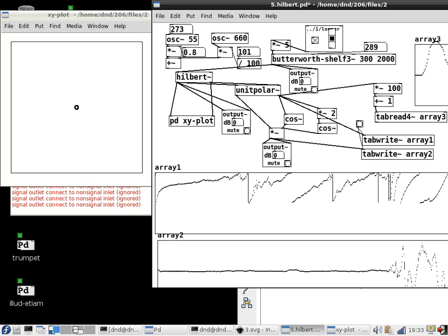What turns out in practice is that if you can manage to pick the 6 strings of a guitar up separately, you can actually set that filter to a reasonable setting for each of the strings, because each one of them only has a couple of octaves of range. Whereas the guitar as a whole has like a 4-octave range, and there's simply nowhere you can put the filter that makes any sense at all. And also, this is a good thing for monophonic signals.